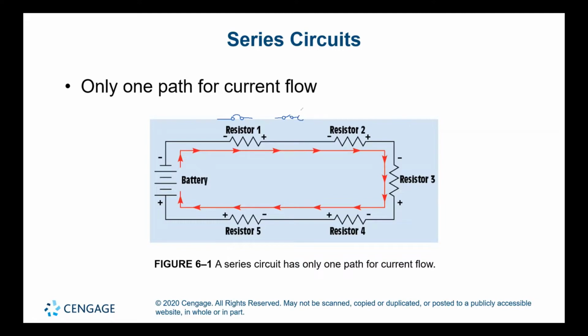So like if we have a light here, even when all these lights are going to be connected in parallel between them, at the end of the day, they are controlled by a switch. And the switch is connected in series with all these lights. And the breaker that is protecting the wires that are connected to the switch and to the lights is connected also in series with the whole circuit, always.